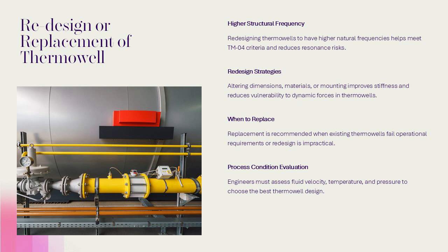Replacement should be considered when the existing thermowell cannot meet operational requirements or when modifications are impractical. Engineers must evaluate process conditions, such as fluid velocity, temperature, and pressure, to select an appropriate design. The goal is to achieve a robust thermowell that withstands operational stresses while maintaining accurate temperature measurement capabilities.